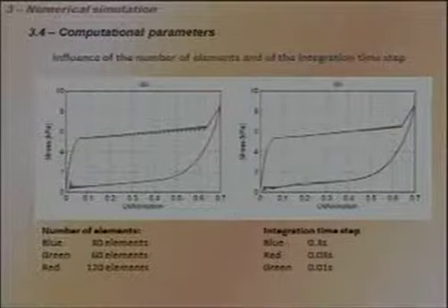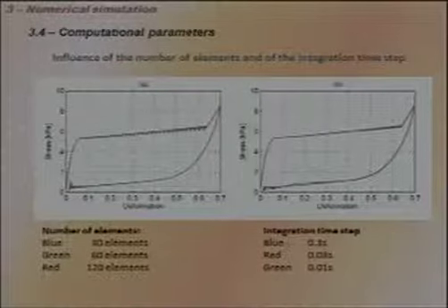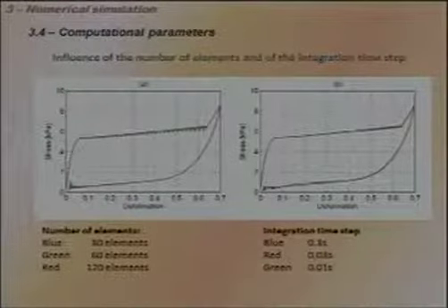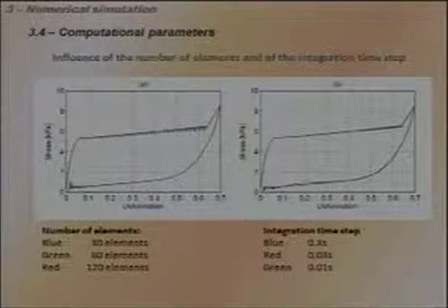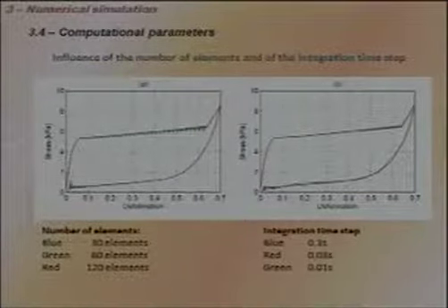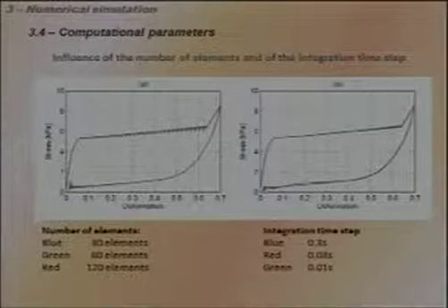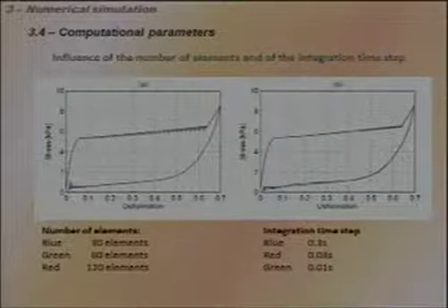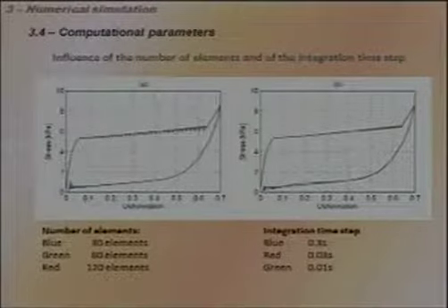So that's the numerical simulation of one cycle. Depending on the number of elements you choose, with 120 elements it's pretty smooth. There is no difference, there is no longer that kind of jump. That's a jump of each string, and that's just about the choice of the integration time step for the integration of the viscoelastic part.